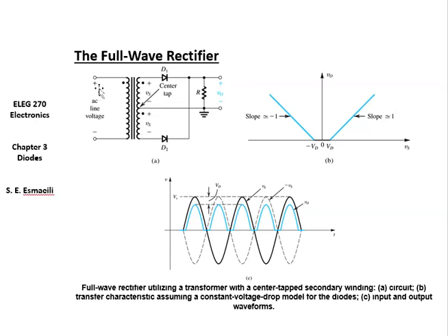So when we are on the positive cycle, okay, so here we're on the positive cycle, so here, for example, it's going to be plus 5, right? Here it's going to be 0. So what will happen, this plus 5 can pass through the diode and will come here, and here is 0. So V out is going to be plus 5.